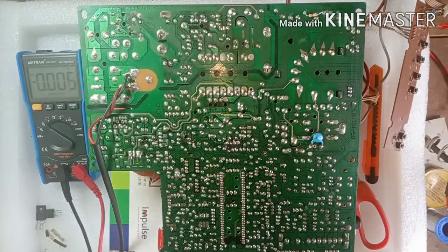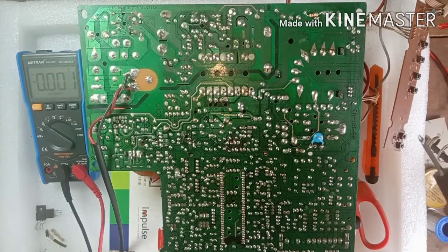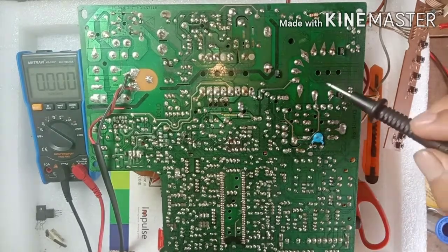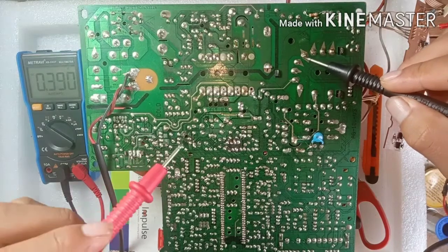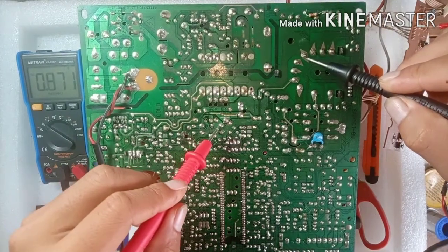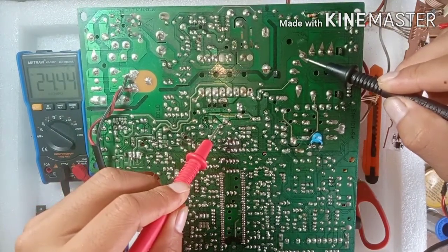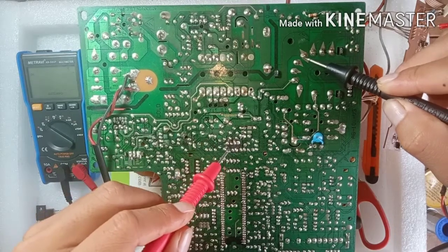So that concludes that all the power supply sections are working great. The individual signals are fine and normal. And so for my next step, since we have vertical faults, however there is normal power for the vertical section, which is the 24 volts DC, I'll check whether the signal really reaches the vertical IC or not. Here, whether this 24 volts really gets into the vertical IC.